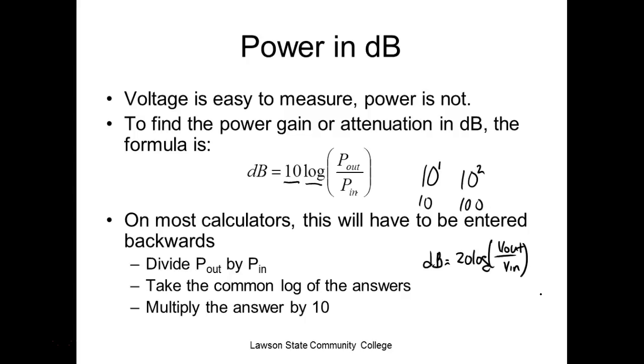But when I talk about my bandwidth, it has nothing to do with volts. It's power loss. But what we've got to do is get power loss relative to voltage, because we can measure voltage. Even on fiber optics, if I've got a transmitter that can generate a certain voltage, and then I receive that light, and that light is converted over to a certain voltage, then I could actually measure voltage loss in my transmitter and receiver and get what we call a power loss. I can get a light loss through the cable, right?